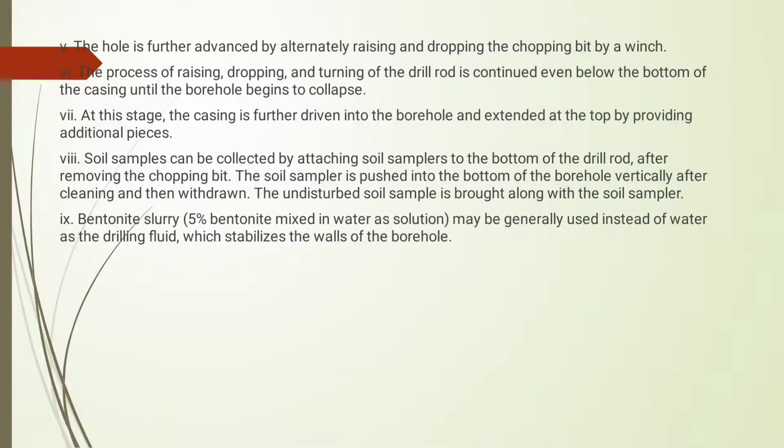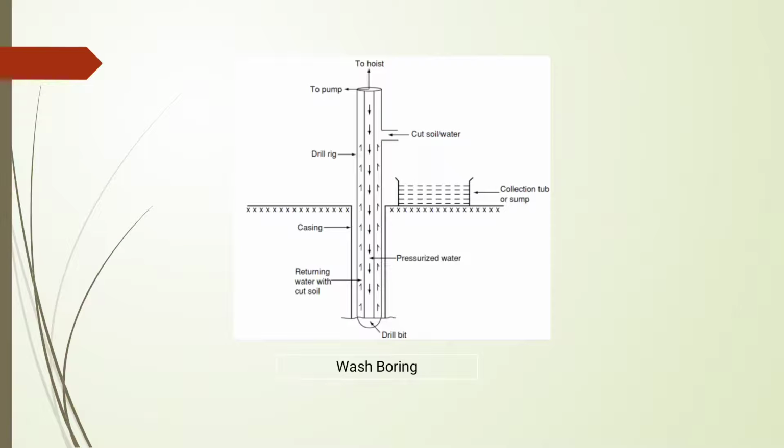Now this undisturbed soil is brought up along with the soil sampler. Sometimes bentonite slurry may be used instead of water as a drilling fluid, which stabilizes the wall of the borehole. So this is a figure.